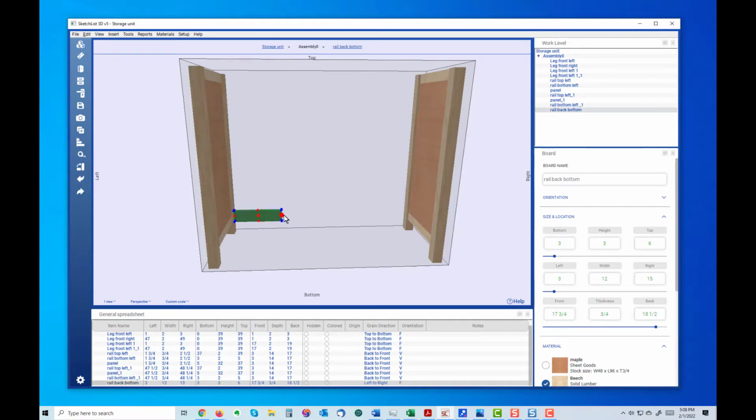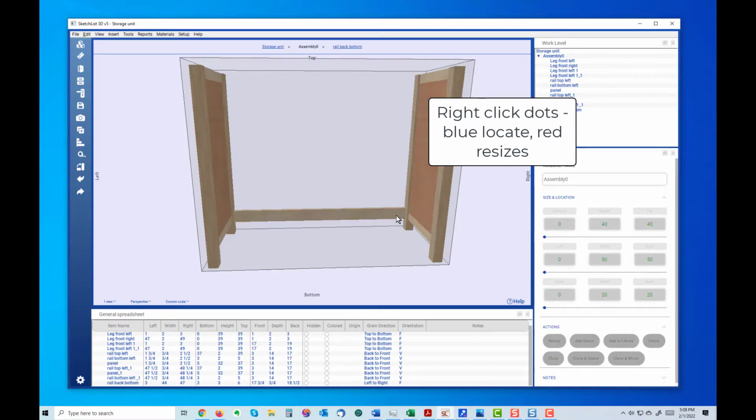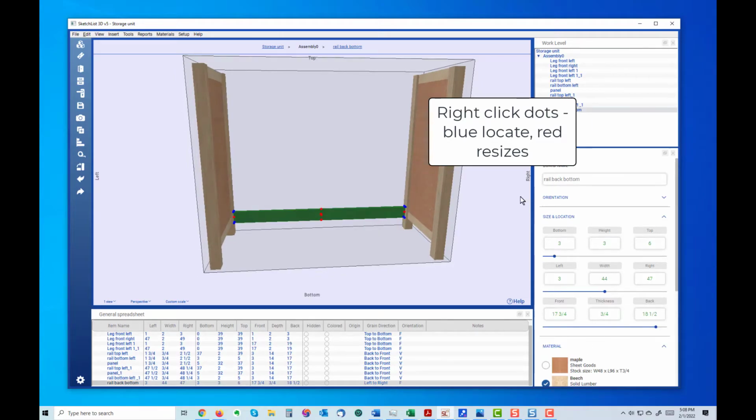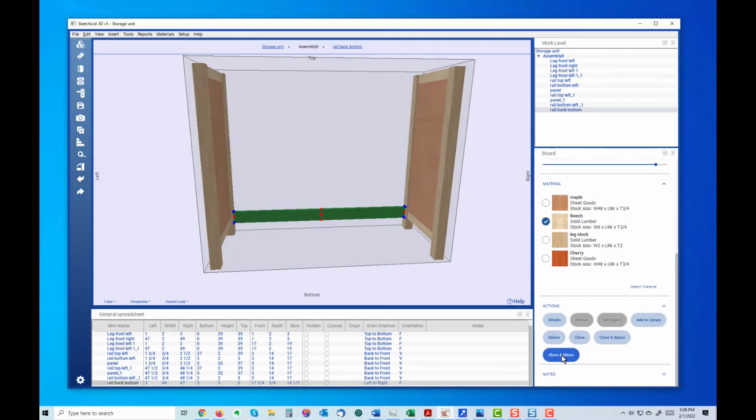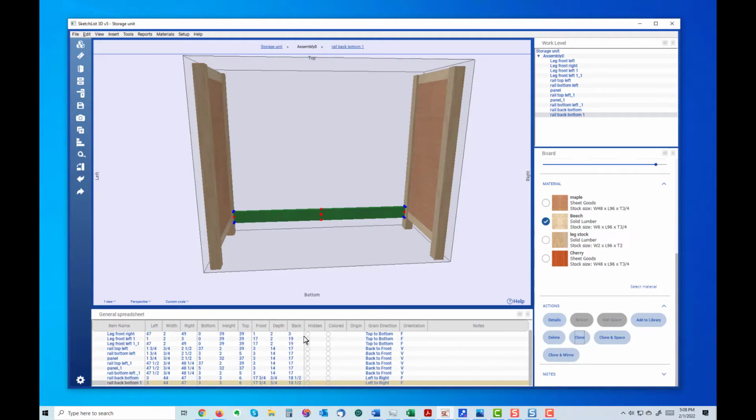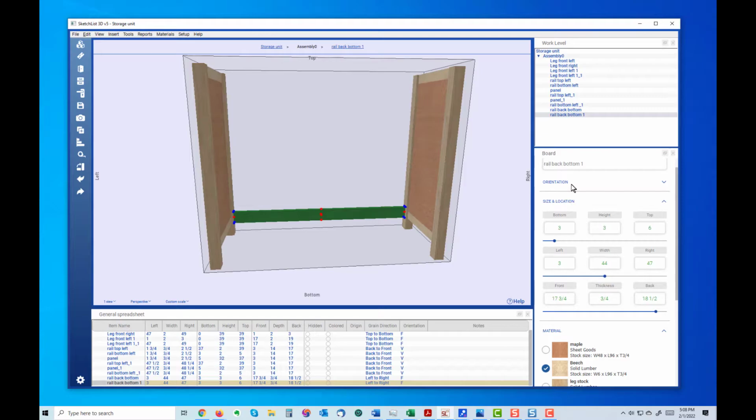This red dot is going to size that. So I'm just going to hold down the Shift key on my keyboard, drag that over, and when it gets close, it snaps in place. While I'm here, I notice the top of that is 39. I'm going to make a clone whose top is 39 inches from the bottom, like that.